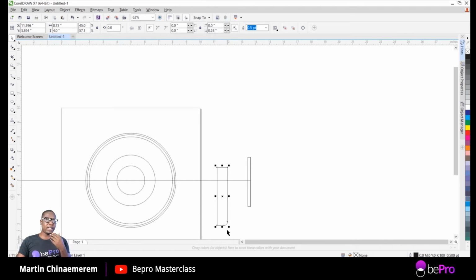Now what we have here is not enough, so we want to increase. Let's say we get to 0.5 radius. Yes, something like this is okay, we can use this. If you still want, you can keep increasing by using the arrow buttons here. The upper one increases, whereas the lower one reduces. So let's keep increasing. So you see, at the point we get to 0.5, 0.75, we have the radius on the bottom left corner of the rectangle shape we created.